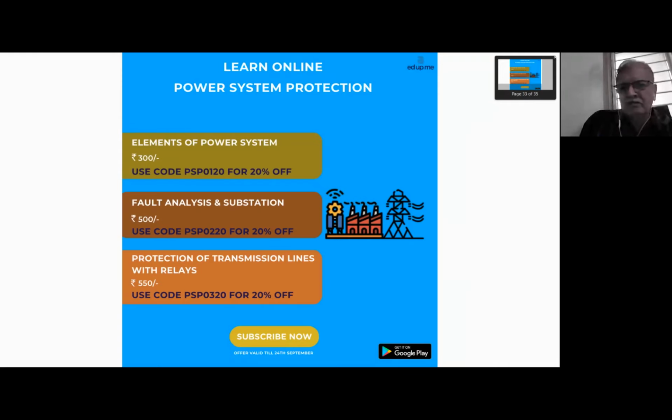It is quite possible. Giving a blocking signal to two relays is also possible, because nowadays there may be more than two starting relays you can use, because people are offering as many as 16 binary outputs. From 16, 4 may be power outputs and the remaining 12 may be signal outputs. All signal outputs can be used for reverse blocking or reverse interlocking.